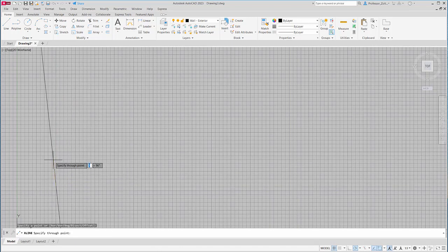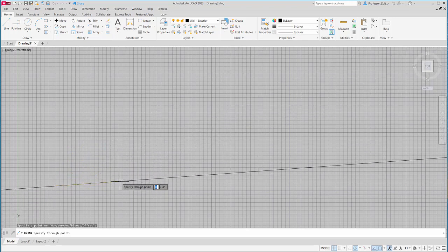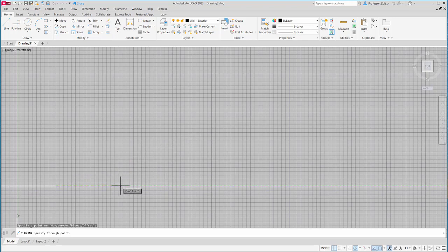And you notice that it generates a line, and as you move your mouse, it snaps to that horizontal and vertical location. What's interesting with this construction line is it stays on after you create a line. So it's different from a line command. I'm going to click on a horizontal position and a vertical position, then I just press enter and it removes the line command.